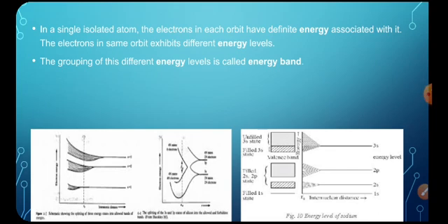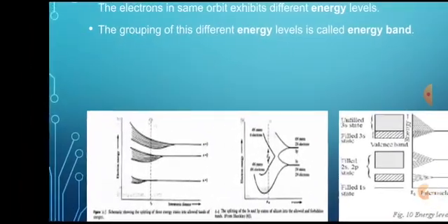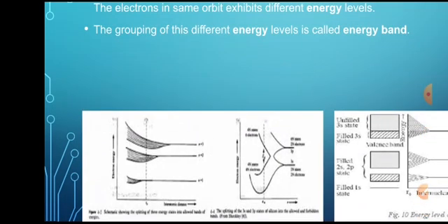Originally identical energies in the isolated atoms spread out to form an energy band. Similarly, for the n state, identical energies of isolated atoms split into two bands, separated from one another by an energy gap. At smaller spacings, there comes a region in which the bands merge with each other. Here you see the bands merge at this level. They split into different energy bands and interact at some level. The lowest energy state that splits from the upper atomic level appears to drop below the upper state that has come from the lower atomic level.